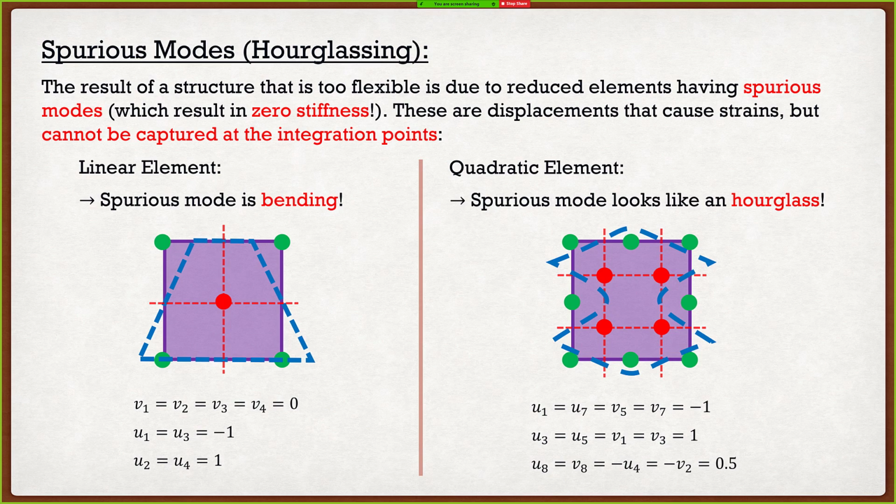At this point, you now know everything Abaqus does. Remember, when we went to modify the element type in Abaqus, we basically had 3 different options. Do we want a triangular or quadrilateral element? You know what both of those are. The next thing it said is, do you want a linear or a quadratic element? You know exactly what both of those are. Now, the final mystery, of course, was, do you want reduced integration or full integration? Now you know exactly what those are.